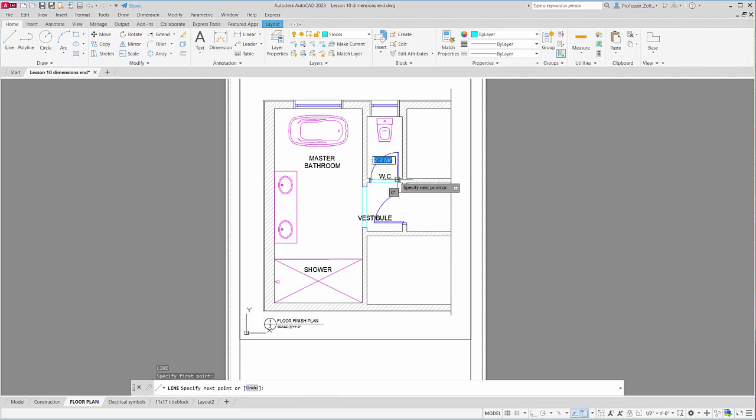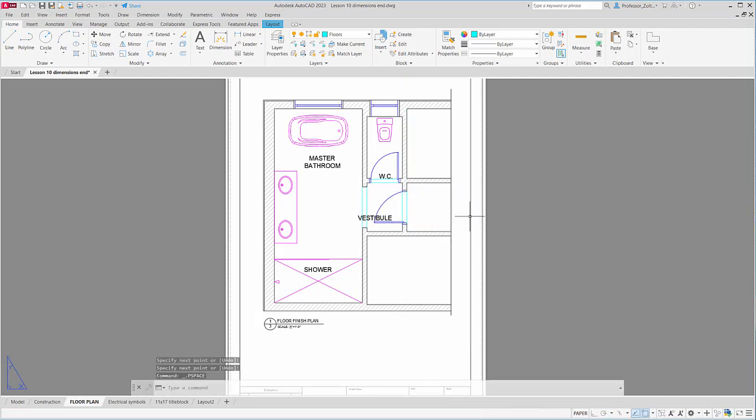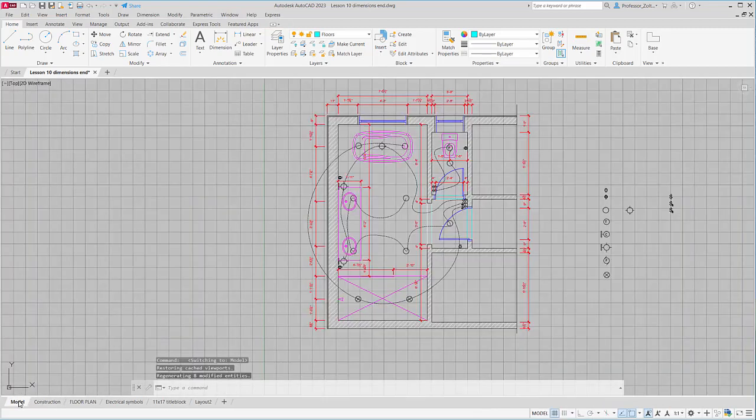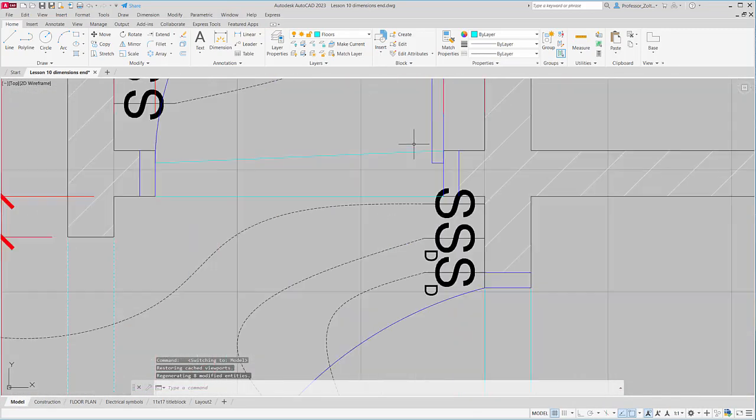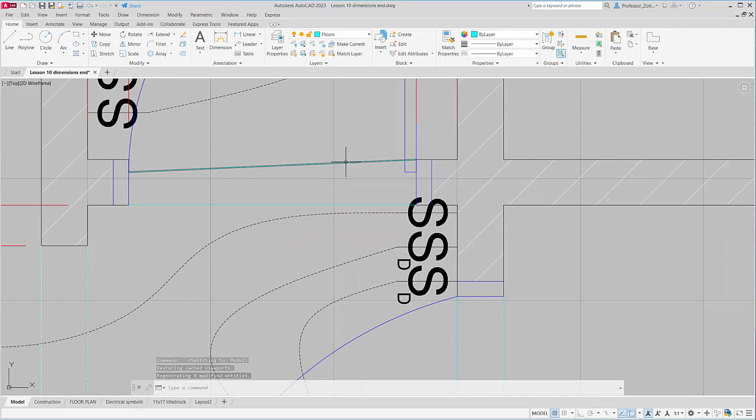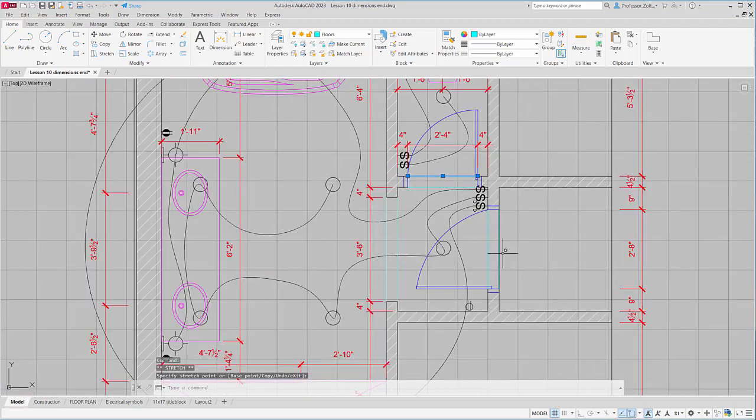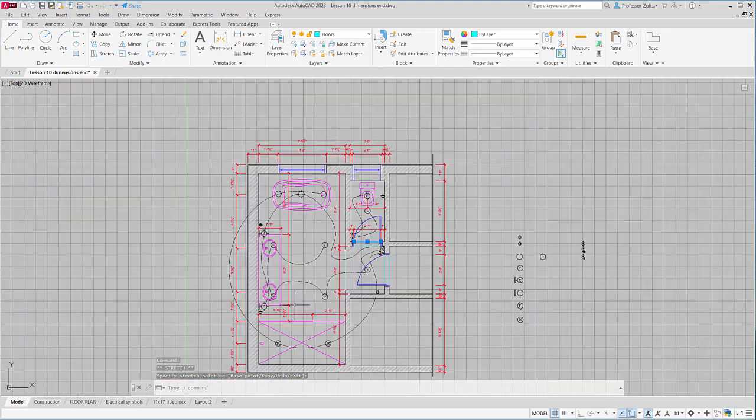And if you're not comfortable drawing this line work in the viewport, just go right into the model space and draw it there. Let's see what happens here. I can draw in here. I just have to be a bit more careful. In model space, look at that. This line is completely off. That's why we have to be careful. It looked good in the paper space, but in model space, it's off. That one works, that one works, that one works.